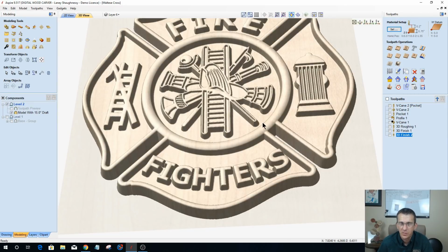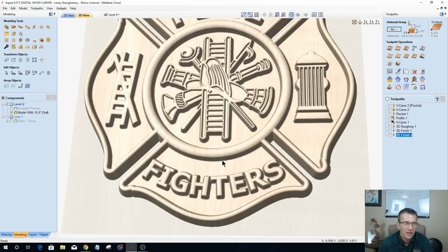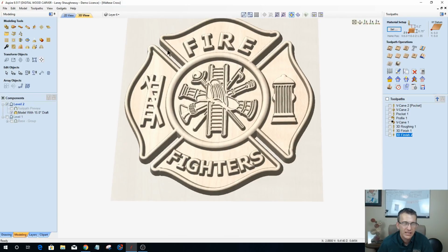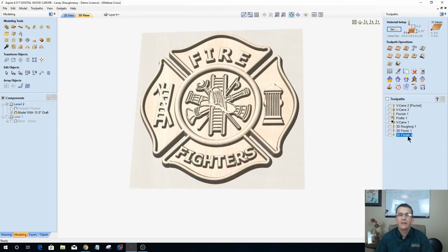In some cases, rest machining is only a few minutes long and helps clean up things. But in this case, a project this size with the areas that it did need to clean up, it was 12 hours, right? Jim, I am talking about a conical ball nose, a tapered ball nose bit. Tapered ball nose bit, also referred to as a conical ball nose. But nevertheless, that is how you do rest machining.